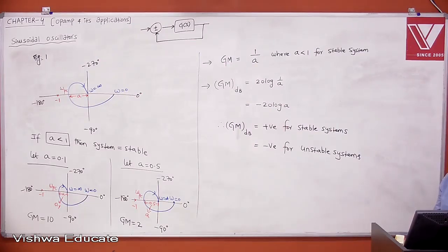But normally we use the term always stable. A 2-pole system is always stable. A 1-pole system is always stable for any value of K. But a 3-pole system may or may not be stable, that depends on K. A 4-pole system may or may not be stable, that again depends on K. Even though you have 10 poles, which is dominant is what is important. People make 1 or 2 poles dominant, then effectively it will be a 1-pole, 2-pole or 3-pole system.